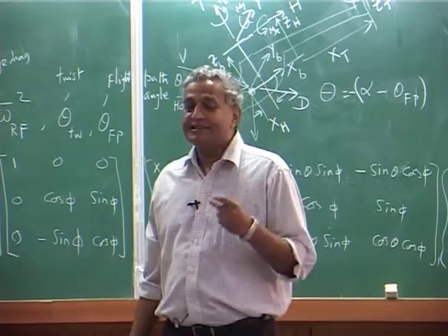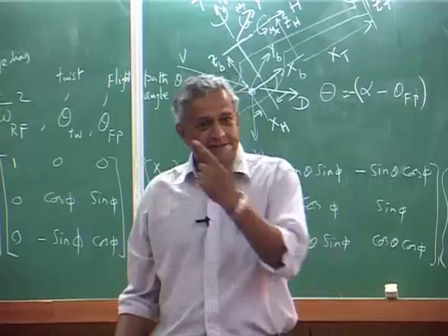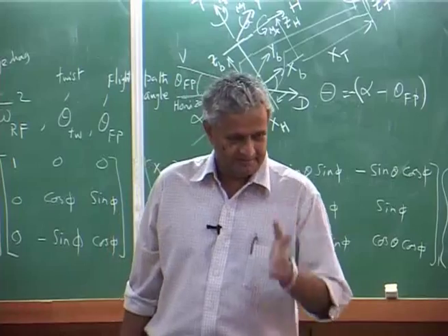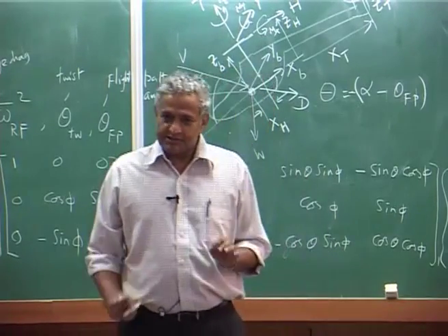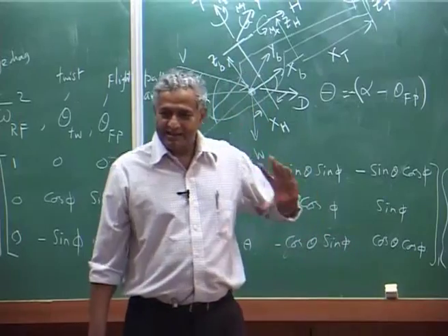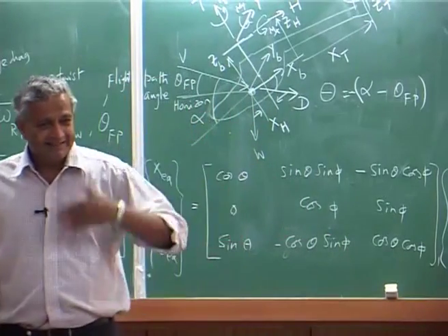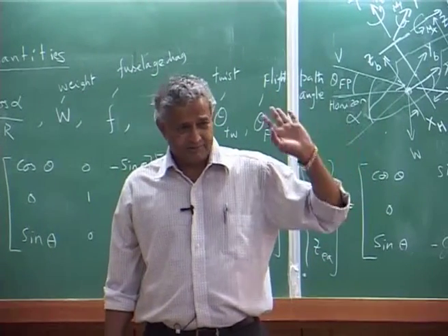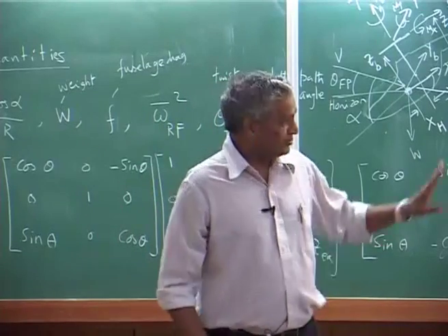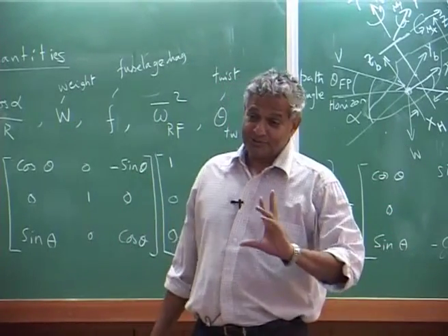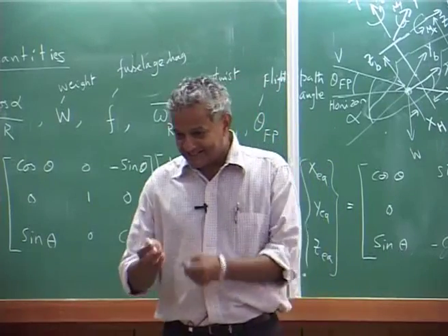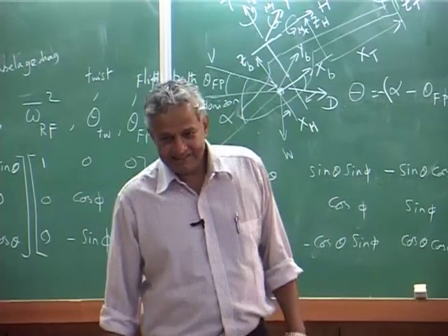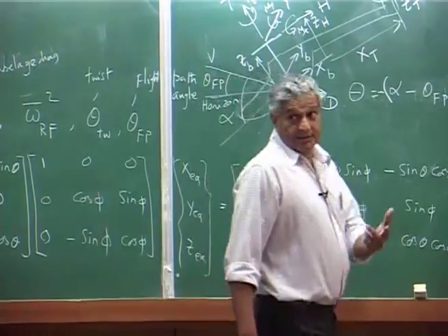Now, what it will do is it will try to relieve the tail rotor load in forward speed a little bit. That is all, nothing more, because the tail operates in a very complex environment. Industries will have a test rig, they will do some tests, otherwise all simple calculation is you take the thrust whatever we have. For the main rotor it is much more complex in terms of pitch angle, etc. The tail rotor is more complex in the aerodynamic environment. And the distance, these are all important.